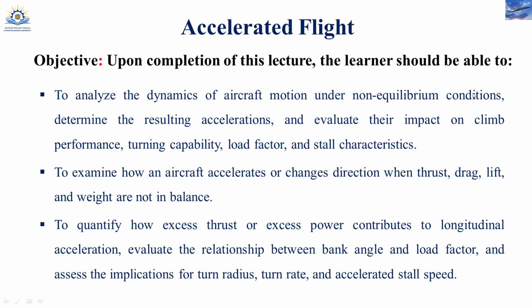Because if the aircraft is performing turning in a very long radius, that means it takes time. So we need minimum turn radius as well as we need maximum turn rate. Turn rate is the rate of change of phi, the bank angle, which is omega.